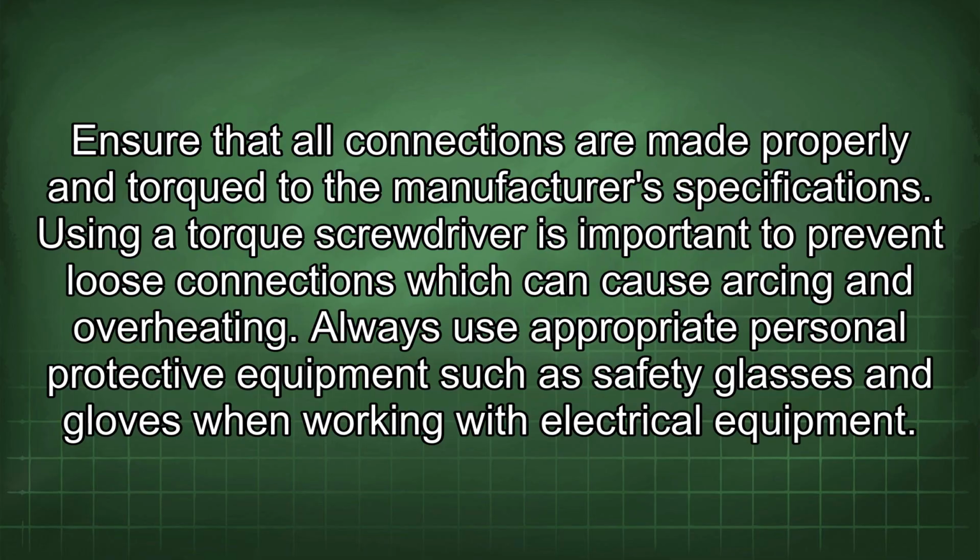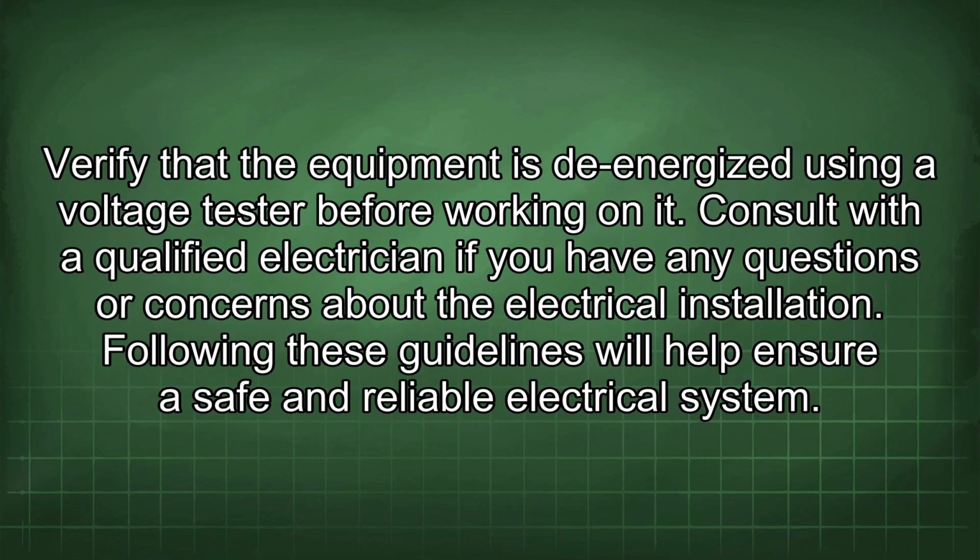Ensure that all connections are made properly and torqued to the manufacturer's specifications. Using a torque screwdriver is important to prevent loose connections which can cause arcing and overheating. Always use appropriate personal protective equipment such as safety glasses and gloves when working with electrical equipment. Verify that the equipment is energized using a voltage tester before working on it. Consult with a qualified electrician if you have any questions or concerns about the electrical installation. Following these guidelines will help ensure a safe and reliable electrical system.